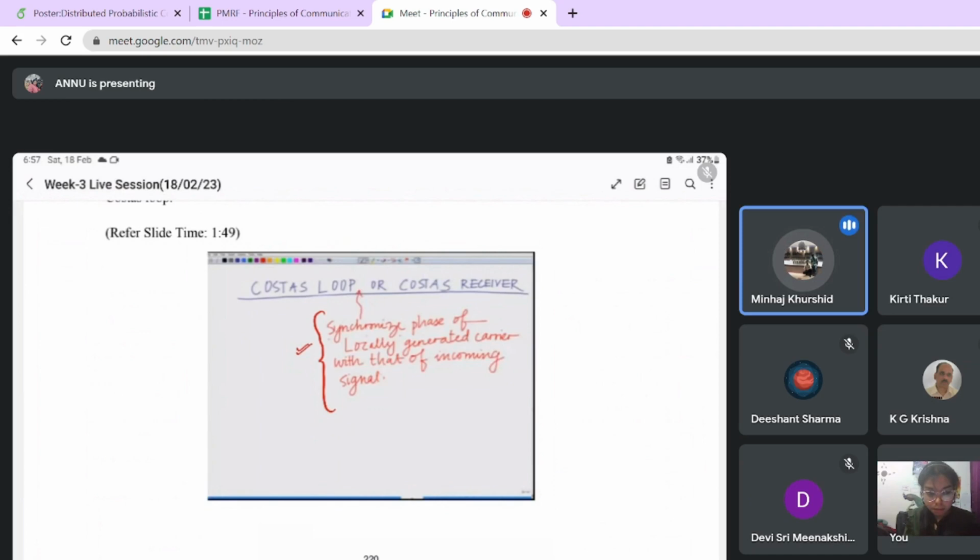Yes, ma'am, I will try. First of all, we have two demodulation paths here. The first one we will multiply by the cos shifted by some phase difference, and the second one we will multiply by the sine factor, and then using an LPF we will get two different terms.